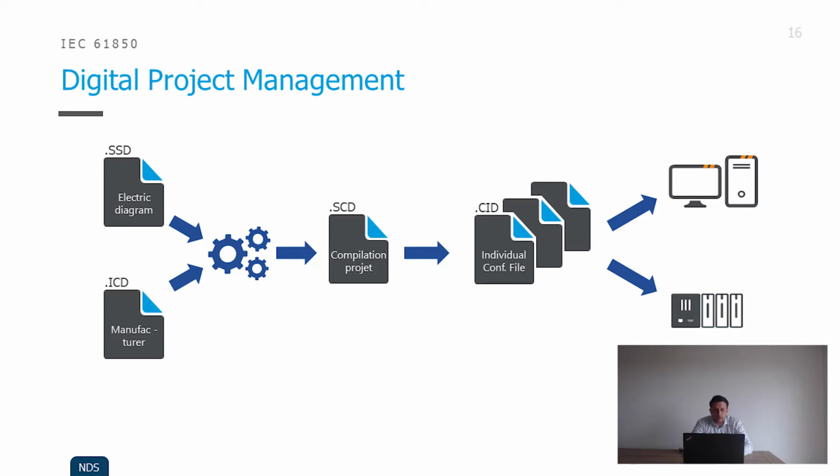So now it is actually possible to extract the configuration information for each IED and then import that either to a Scada client, an RTU, or put the configuration directly into the IED itself.